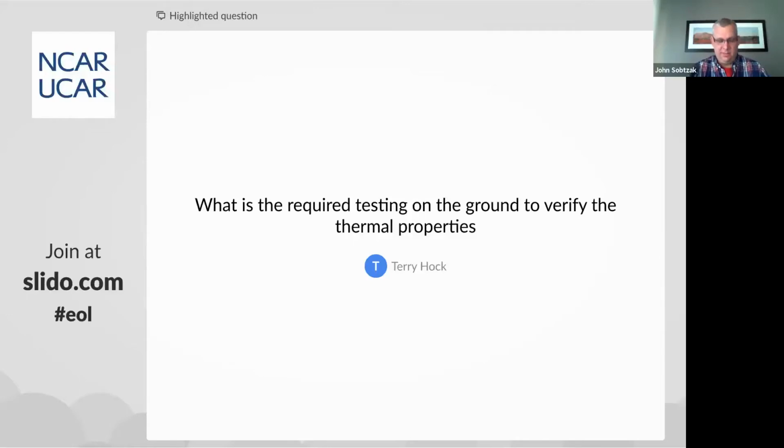Even before you put it in a thermal vacuum, you put it in a thermal chamber with an atmosphere, and you run it up to very high temperature and very cold. You have the wires coming out of the temp chamber on the side, and you turn the system on and off, and you test the system over temperature extremes. You do that mainly in a temp chamber that has an atmosphere, because it's easier to heat and cool things when you can use air.